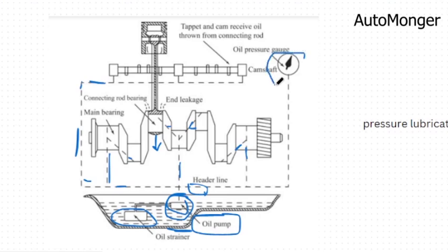And of course, like I said before, I've explained about the oil pressure. It's meant to check the pressure and make sure that the pressure is always normal. When you have a lot of pressure in the system that can cause damage to the system, the pressure relief valve is going to open and release the pressure from the system, and then the system is normalized again and the engine continues to work. So guys, that is it about the pressure lubrication system.